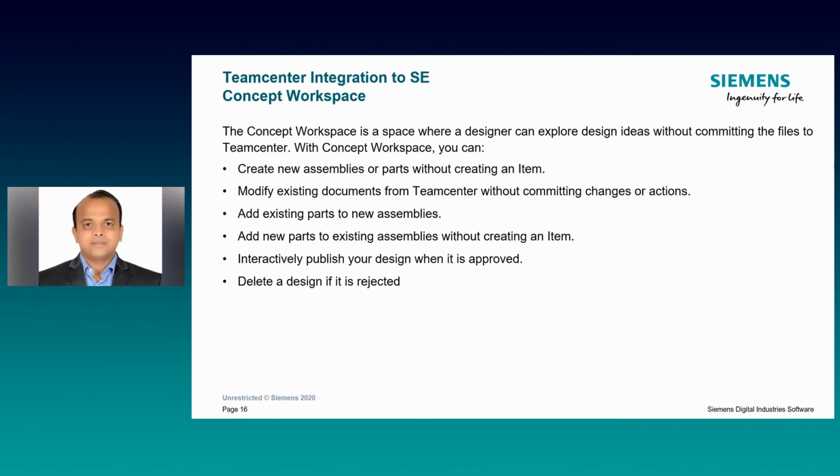As the name suggests, it's a workspace or a volume where a designer can explore new ideas without committing files to Teamcenter. You can create new assemblies or parts and develop new concepts within the workspace, or you can create new concepts by modifying the existing documents from Teamcenter by retrieving the documents to your workspace. All new documents and retrieved documents remain within the concept workspace until those get published back to Teamcenter.